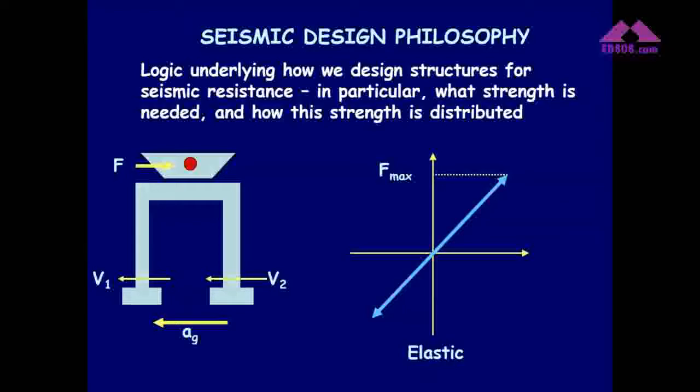So first I would like to talk generally about seismic design philosophy and how buildings react to seismic excitations. When an earthquake occurs, the ground moves. And when the ground moves, the earthquake forces act from the mass inertia center of the building. Due to this earthquake load, some internal mechanisms occur in the structural elements like columns and beams. Here is an example of a double-bent bridge pier, where the force acts from the mass center, and the result is shear forces on the bridge piers.